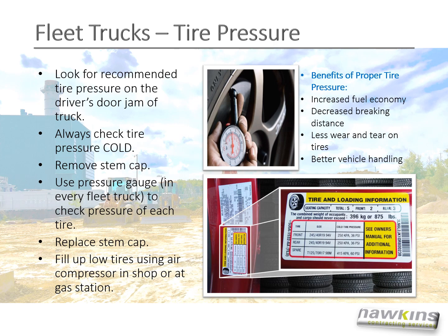Checking tire pressure. Look for the recommended tire pressure on the driver's door jamb of the truck. Always check the tire pressure cold. Remove the stem cap. Use a pressure gauge to check each tire. Replace the stem cap. Fill up low tires using the air compressor in the shop or at a gas station.